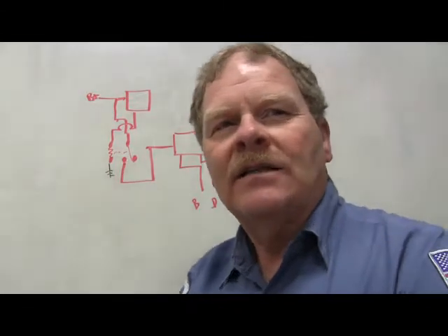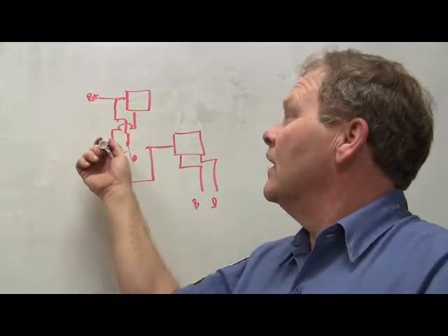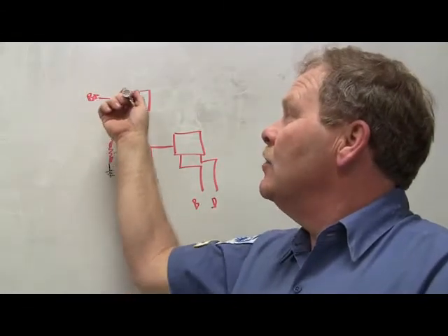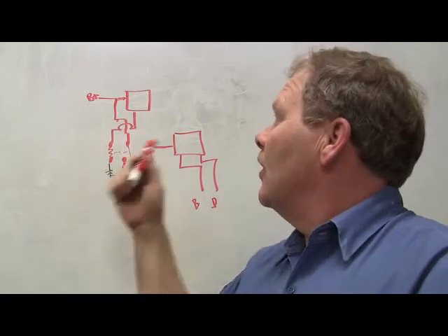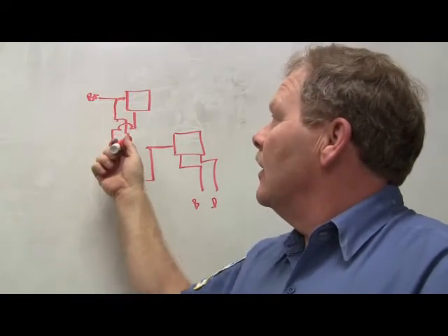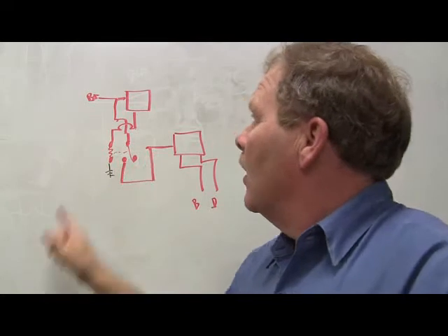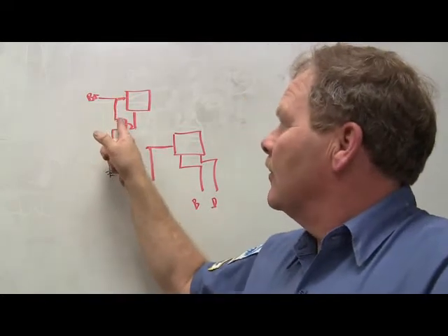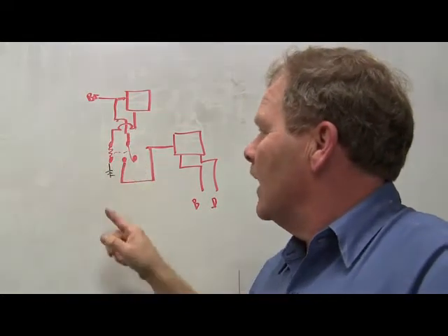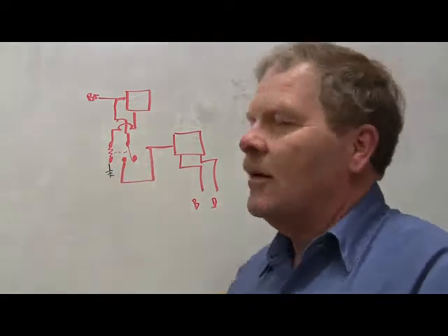You're adding a relay so that your original switch is closing the relay, and the battery power that used to go through the switch to burn the lights is now diverted through the relay, and all of the current is going to be flowing. It's going to be bypassing the switch, going through the relay. So when the relay closes, the lights come on.